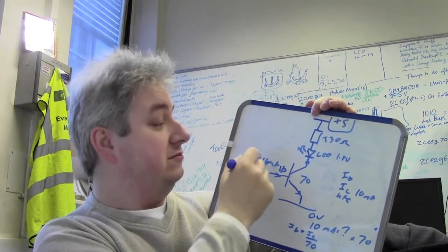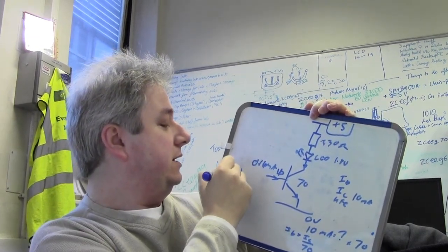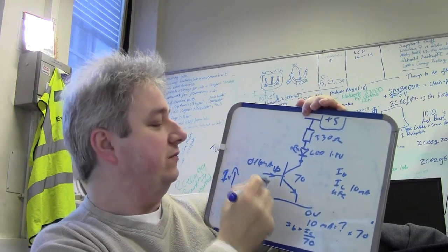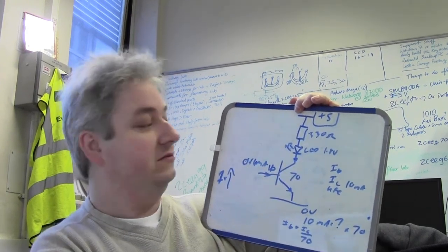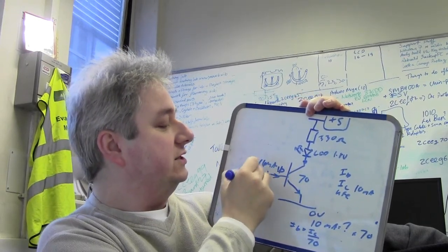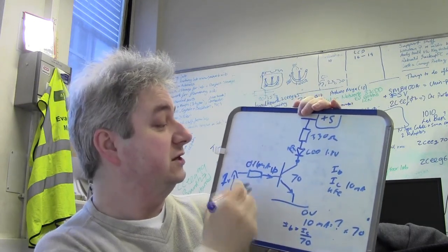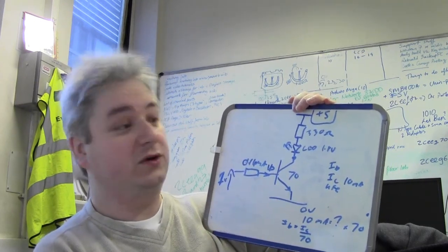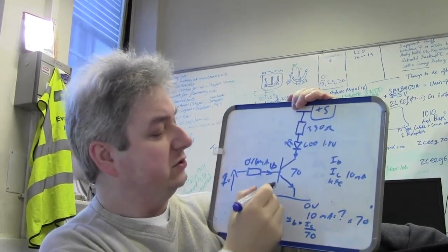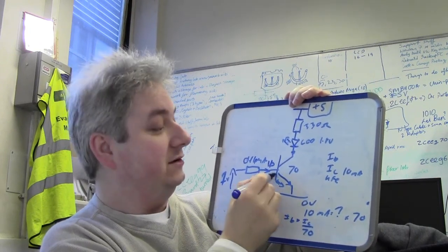How do we get that amount of current? We've got 1 volt on input. We need 0.14 milliamps flowing. Use a resistor again. Resistors resist current. We can drop voltages, and we can work out our current working into the base using Ohm's law. Slightly different though, because we do get a base emitter drop.